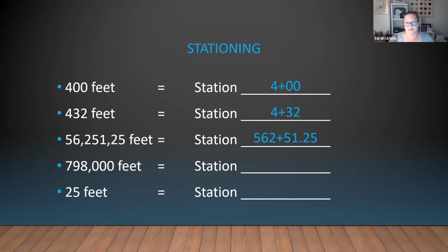So let's try the second to the last one. 798,000 feet. That's it. So it's much easier to say, hey, I'll meet you out at station 7980. Right? You know where you are, you just get to drop all those zeros. Last one. That's it, plus 25.